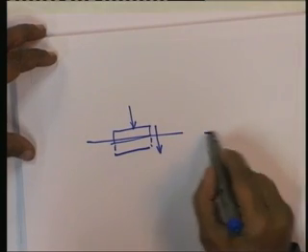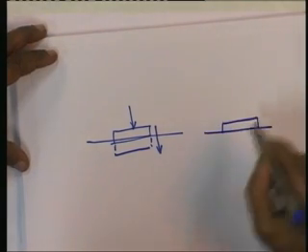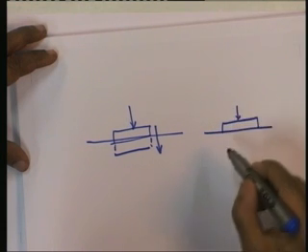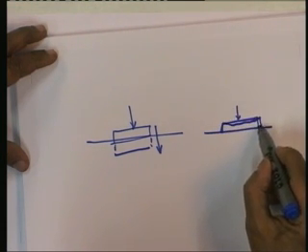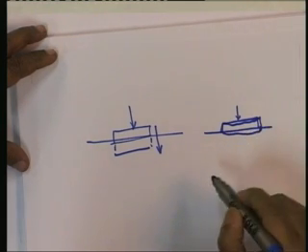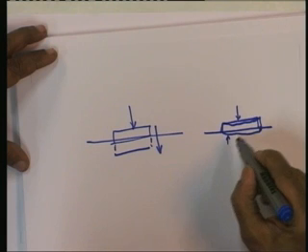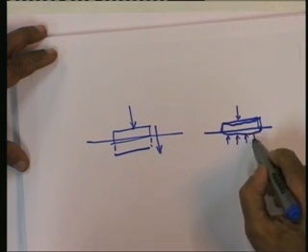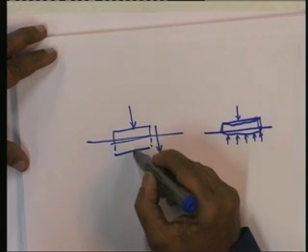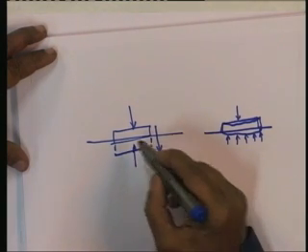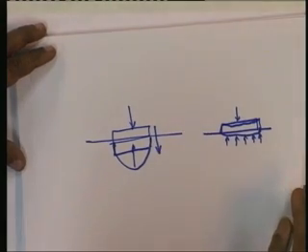Now, if on the other hand this foundation is a flexible object, then when I apply a load, this is likely to bend like this, which means that it will experience uniform stress from below, whereas in the rigid case it may experience very large stresses at the center, but lesser stresses at the edge, and it may have a stress distribution like this.